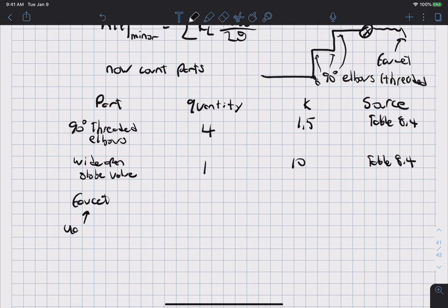And in the instructions it says U averaged is based on the pipe velocity. So if you have a reducer or an expander and a vendor gives you a loss coefficient, they will often tell you what velocity that loss coefficient is based off of, whether it's the velocity in the small area or the velocity of the fluid in the larger of the two areas. In this case we were told it's based on the pipe velocity, which would be the average velocity that we've been using most of the time. And that loss coefficient is 2, and that was given in the problem statement.